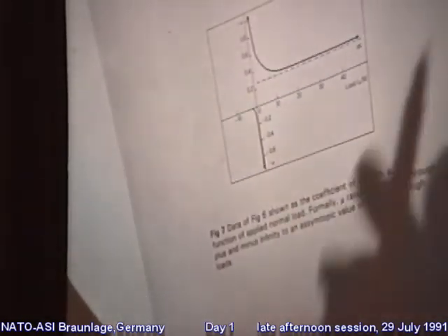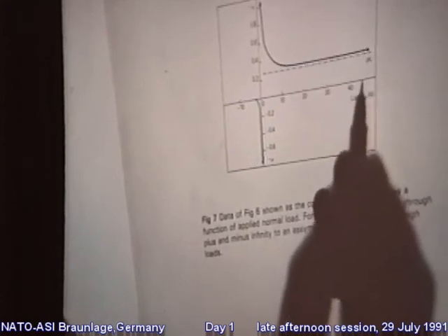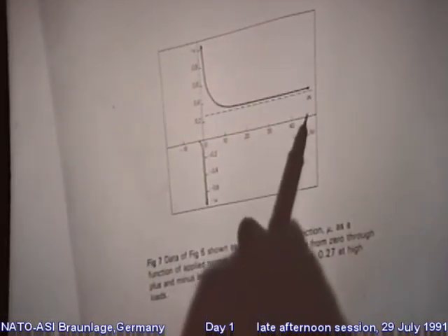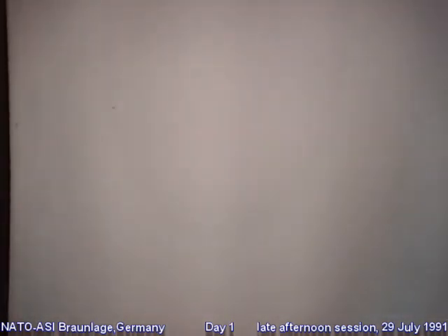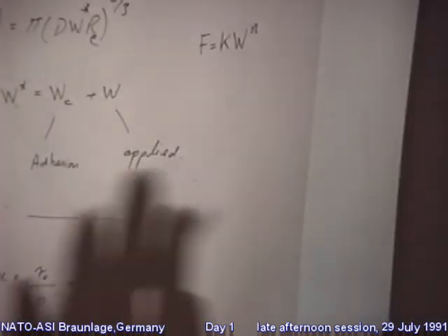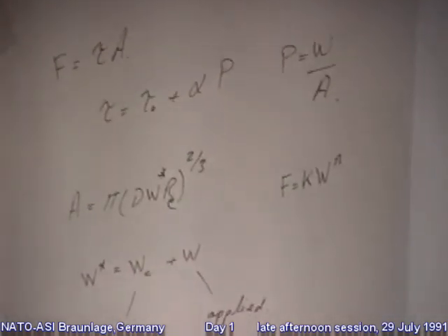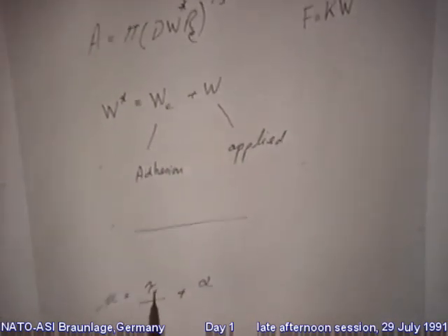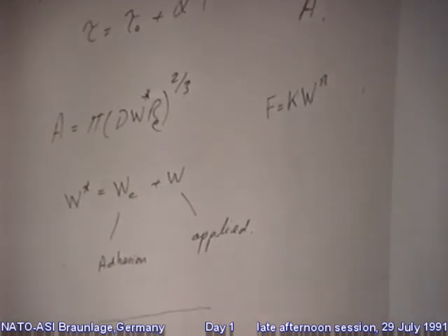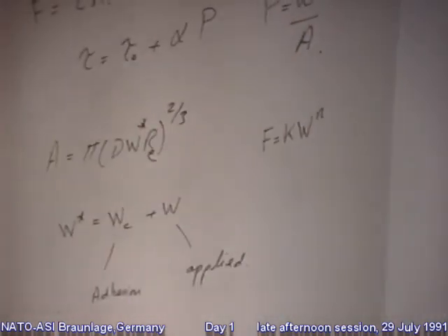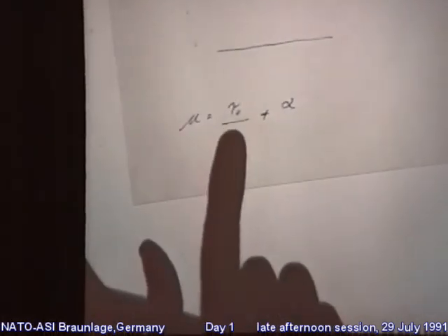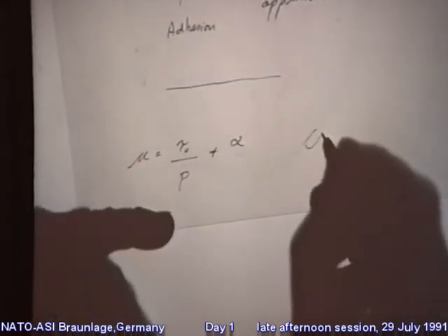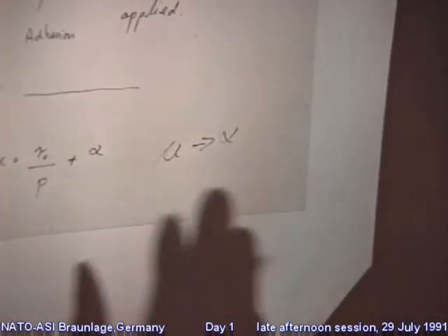Now can I just finish by saying this alpha here. Professor Dowson mentioned pork fat this morning, did he not? Yes. Pork fat. Marine slideways and Coulomb. Yeah. Well, if you transcribe these relationships, you can write the coefficient of friction as tau naught, that's that parameter there, upon P, that's the mean contact pressure, and that's alpha. Now, of course, when the contact pressure is high, as it would be on a marine slipway, this term is small compared with that. So mu tends to alpha.